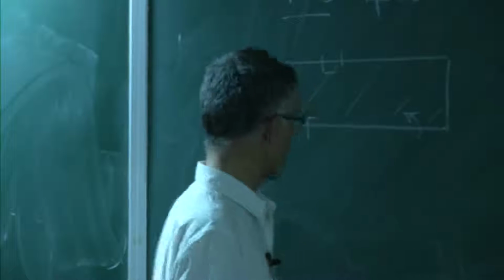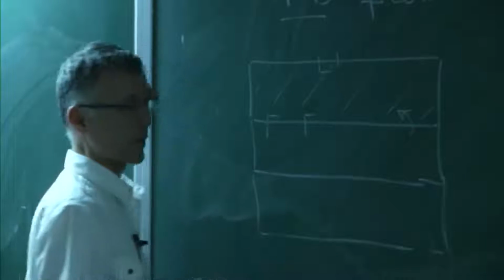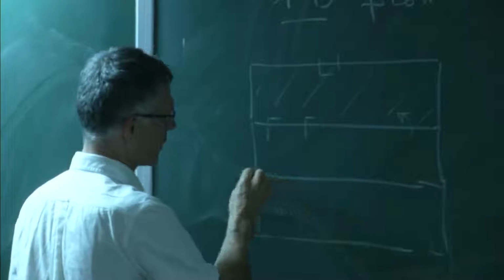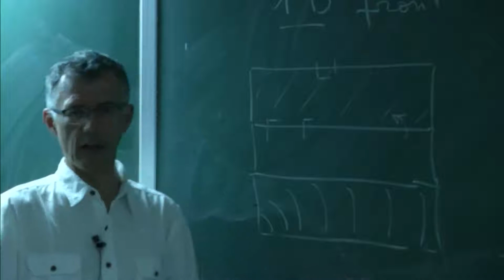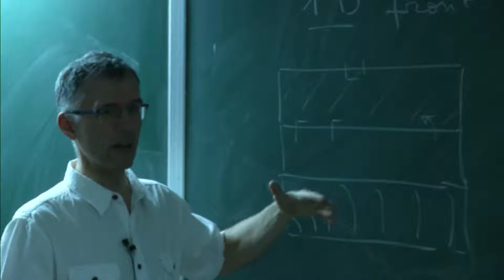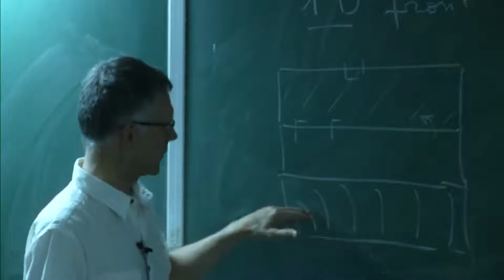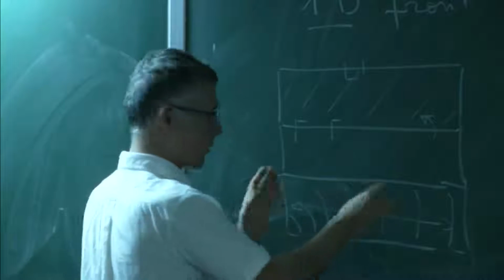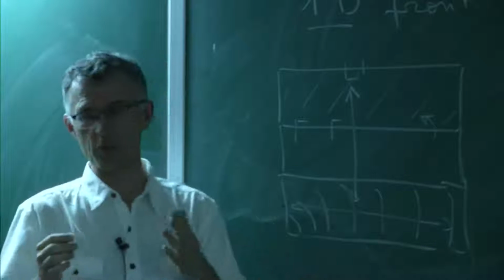There are two scenarios when these things happen. The first scenario is what you call the good scenario. If you have this building here, you have combustion here. Combustion goes from one end to the other. Everyone is dead here, but the building survives because you stay in what we will call the deflagration regime. The pressure waves are small. But the bad scenario is that if this wave now, for some reason, goes to detonation, not only do you kill everyone here, but because the structure dies, you kill everyone on top of it. So the main issue for safety is to make sure that even if you have a flame, it will remain subsonic.